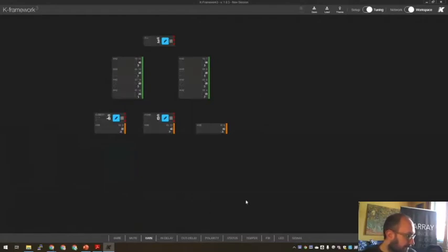If I go on the gain view, I will have a plus 3 on the old system, minus 6 on the subs. And here at the moment it's very small because it's made for the amplifiers, but we will make it bigger for the Mugello in the future. On every device, you can see the gain of that single device. So in this case, plus 3 on the tops, and the external subwoofers are minus 3, the internal subwoofer is plus 3, because I removed the 6.